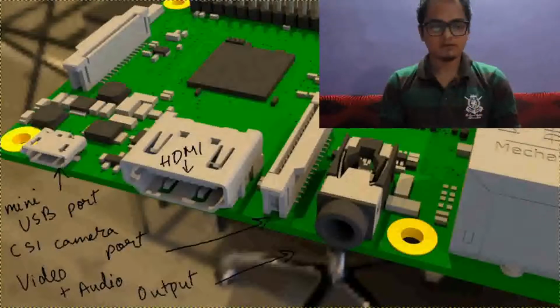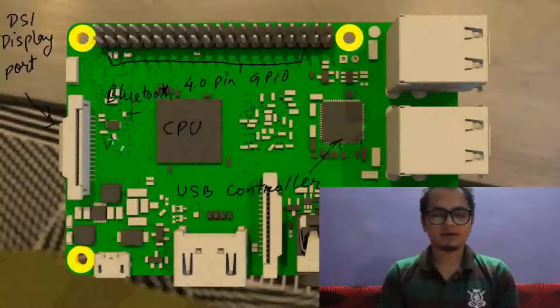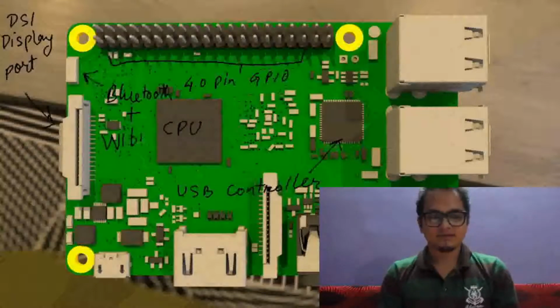On the left side of the Pi, we can see the DSI display port through which we can connect small display devices. Just adjacent to it, we have the wireless LAN and Bluetooth module. The wireless LAN has a dual bandwidth of 2.4 GHz and 5 GHz, and the Bluetooth that is being used in this module B+ has a version of 4.2. Coming to the most important component of the Raspberry Pi, we have the Broadcom 64-bit quad-core CPU, which provides us with a clock rate of 1.2 GHz.